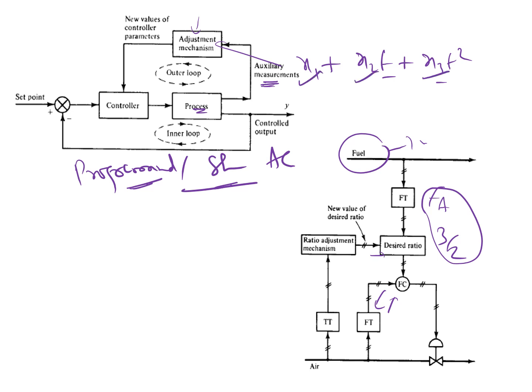This air temperature is T, and to this the adjustment mechanism is added. So keep on tuning the values and get the controller parameters. Then check whether that non-linearity will be addressed. If not, again change this value and this value, and get the new controller parameters. Add to that, then that is given to the process and check for the addressal of non-linearity. So likewise, you can keep on changing this.